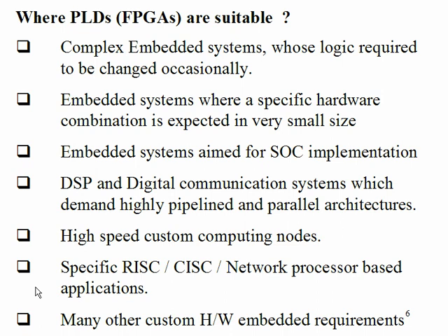Got the point? But wherever I have fine, refined jobs, like if you take the DSP, in the DSP case we can shortlist and say 15 operations are there: reading from RAM, writing to the RAM, very general things, MAC operation, something like that. I can easily say 20 operations. These are 20 operations which I may do in a variety of sequences, in a different manner depending upon the application, but ultimately I do 20 jobs only, usually. So RISC is suitable for it.